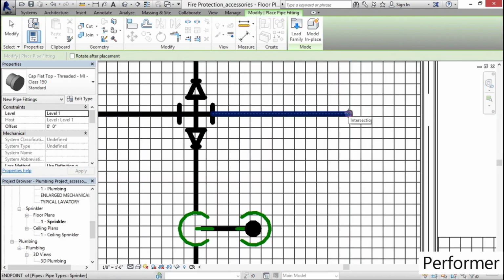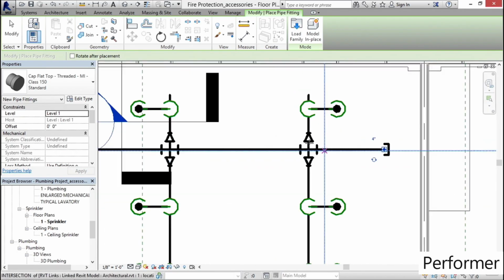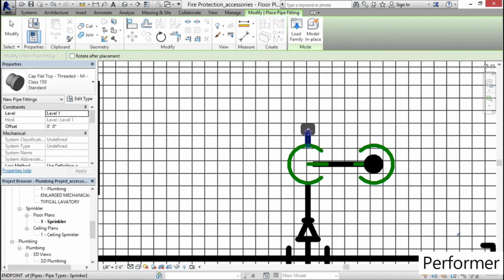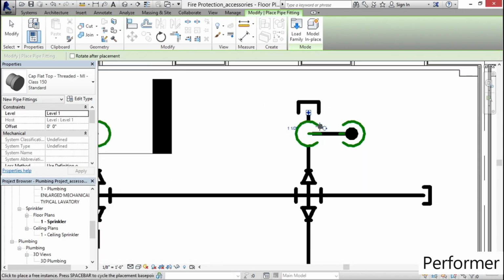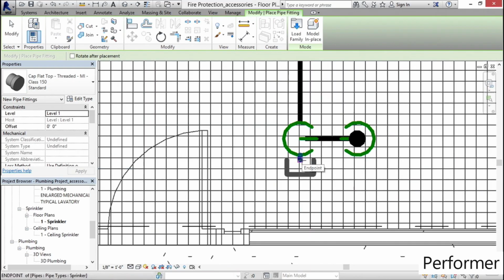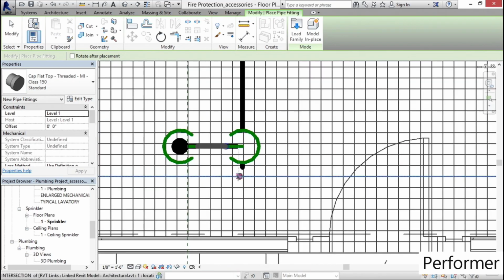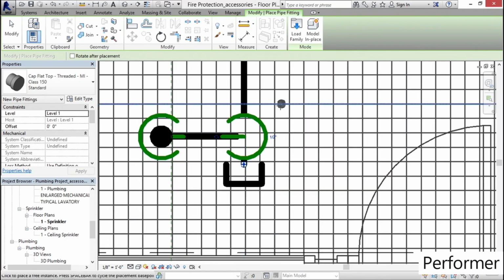Aim into the pipe and pick it. In this case, Revit does know what size it's supposed to be, and will put the symbology in plan for you. Make sure you're snapping to the ends of the pipes, that way Revit doesn't have a cap floating out in space.